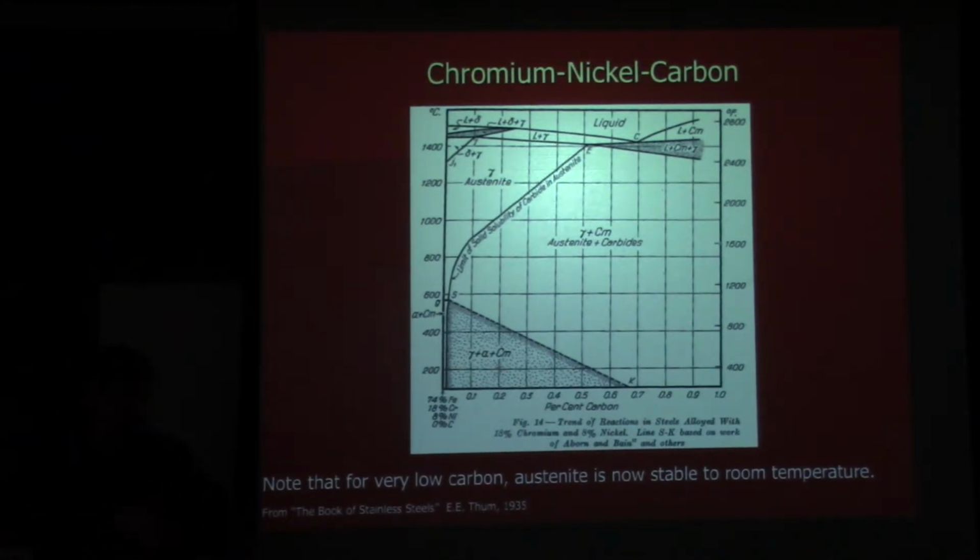We all know that if you put lots of things in liquid nitrogen and then you drop them, they shatter. That makes for some fun engineering experiments, right? But you still have to be able to move that cold stuff around. Well, you put it in a container that's made out of austenitic stainless steel. That grade or grade family maintains its toughness because it's austenite. It's austenite from liquid nitrogen temperatures all the way up to the point at which you start to melt it. So why would it make a difference if it's austenite?